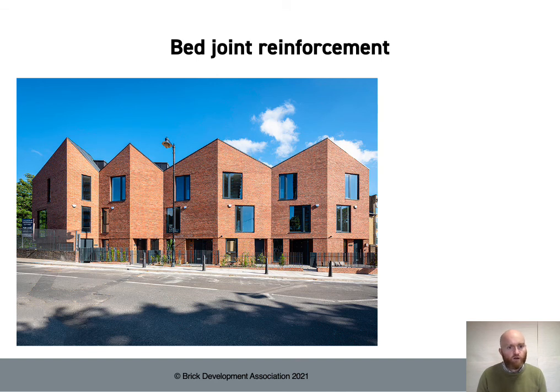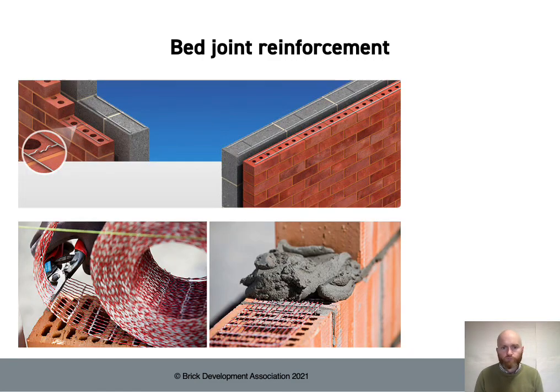And you can see from this project, actually you've got these openings which are offset going up the building, and the loads within that brickwork, you're then forcing them on a slightly convoluted path down like this, and you have the potential for some tensile forces building up there. So just the introduction of some bed joint reinforcement within these areas can just make sure that you're covered in terms of that and prevent any unsightly cracking from developing in those areas.